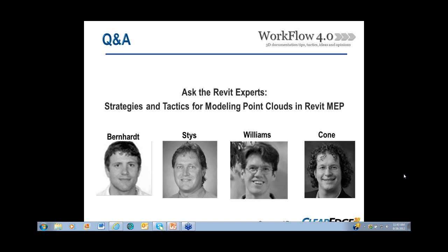For us right now, it's really our ability to manipulate the point cloud data and extract information and model information from it accurately. I could go into a lot of detail on where that falls apart right now. We don't use Cyclone. We pretty much bring the point clouds into Revit and model on top of it using either CloudWorks for Revit or I guess Imagine It now, their scan-to-BIM plugin. Those have been our older workflows, and it's a pretty tedious process. It just takes a whole lot of man hours. That's the biggest challenge. Just very, very slow and manual.